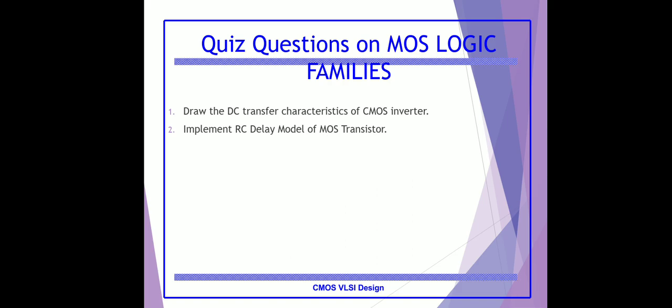Quiz questions on MOS logic families. First, draw the DC transfer characteristics of the CMOS inverter. Second, implement the RC delay model of the MOS transistor.